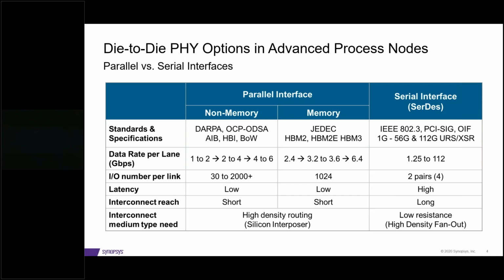Would it be good to define that? Because obviously, if you're trying to drive a really long link, then there's a tremendous amount of DSP and a tremendous amount of forward error correction and the like. So that adds huge amounts of latency. But if you have an extremely short reach and you're just going from a mux, from parallel to serial, sure, it's going to be higher latency. But are we talking a few tens of picoseconds or 100 nanoseconds? We should define that before we say that it's a killer or not, if you see what I mean.